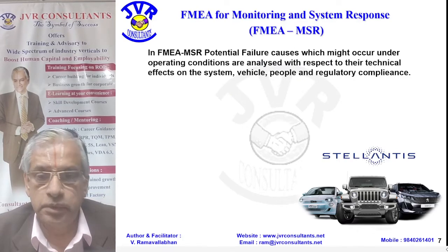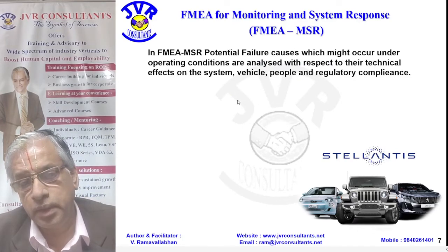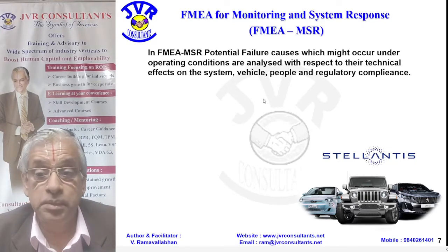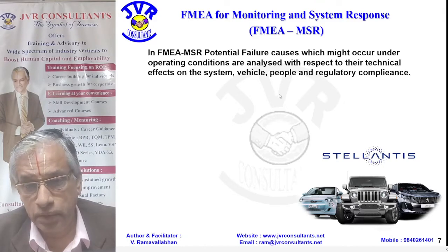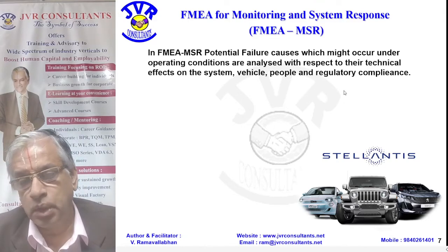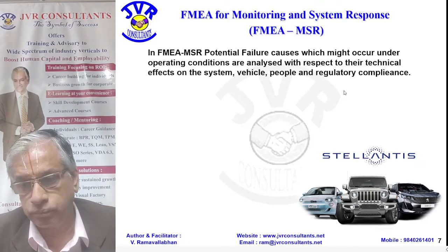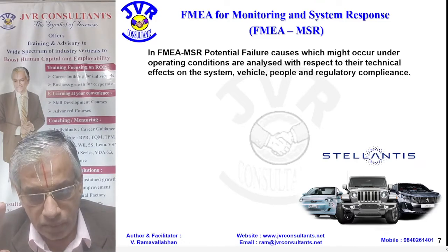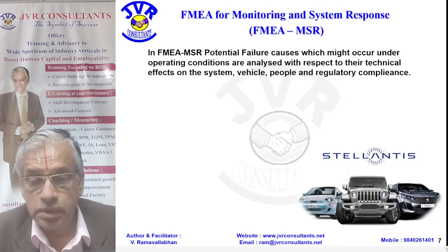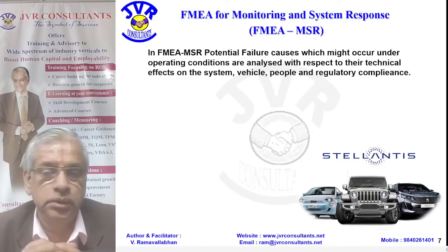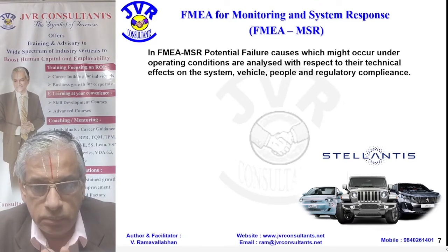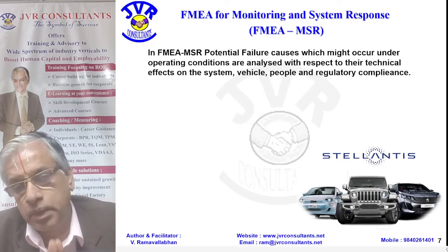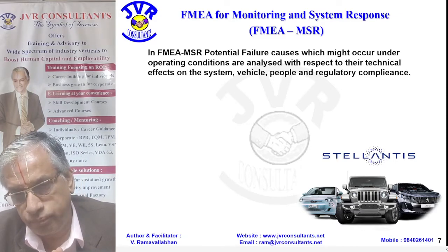Then FMEA-MSR. In FMEA-MSR, potential failure causes which might occur under operating conditions are analyzed with respect to their technical effects on the system, vehicle, people, and regulatory compliance. Now, one thing you have to understand: in the reverse FMEA, the product has not gone to the customer. The product is still with us. So, we are studying our FMEA, whether our FMEA is robust. Is it effective?